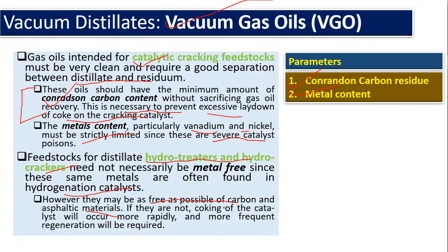Otherwise the catalyst will coke up more rapidly and more frequent regenerations will be required. So ultimately here you have to control the coke concentrations, but don't worry about the metal.